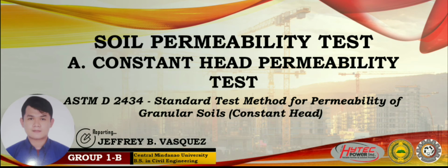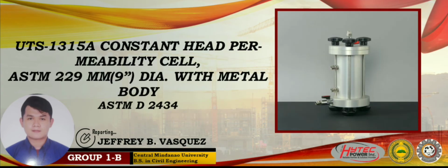Soil permeability test. Constant head permeability test, ASTM D2434. One important equipment of this test is the constant head permeability test apparatus, also known as the UTS 1315A from UTest. And these are used to study the behavior of relatively coarse-grained soils.